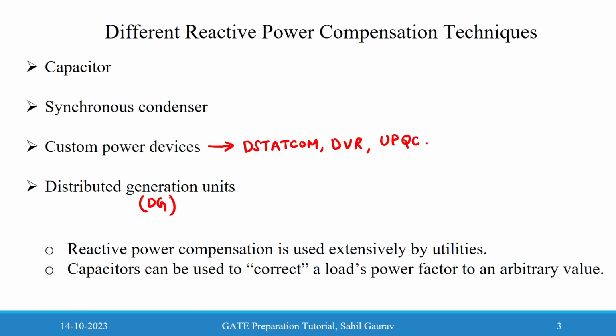Among these different techniques, reactive power compensation is used extensively by utilities, and by using the capacitor you can make the load's power factor to an arbitrary value. We will see the example for this, how you can use the capacitors to make the power factor at your base.